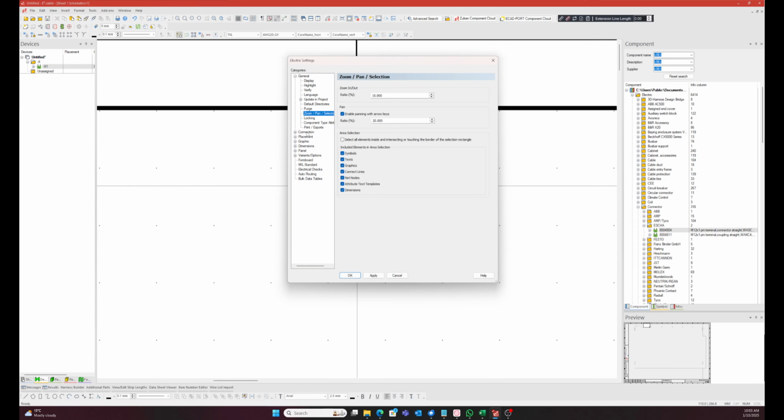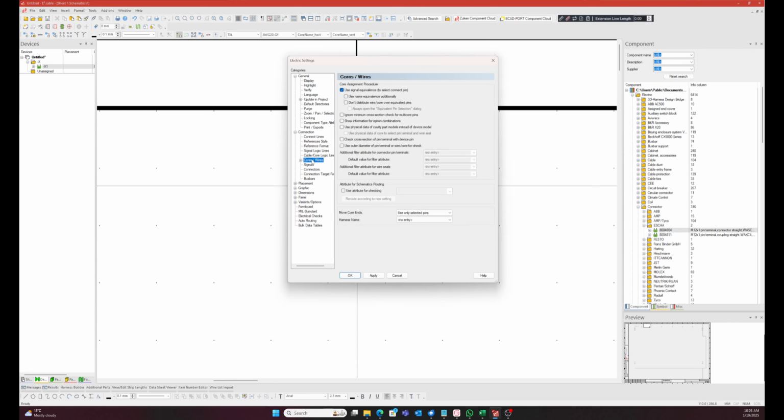And then the next one is connection under the cable core logic lines. I like to by default switch on the use cavity, these two. What that means is once you connect into a connector with the wire size, it will try and match the connector pin terminal. If the wire size is too big, too small, assuming it's defined in the database, it won't let you connect the wire, and if there's multiple pin terminals, then you'll pick the right pin terminal based on the wire size. But again, a good one to have on by default. Otherwise, you can start to do drawings and then you realize it hasn't been switched on, and you've put wires that don't fit.